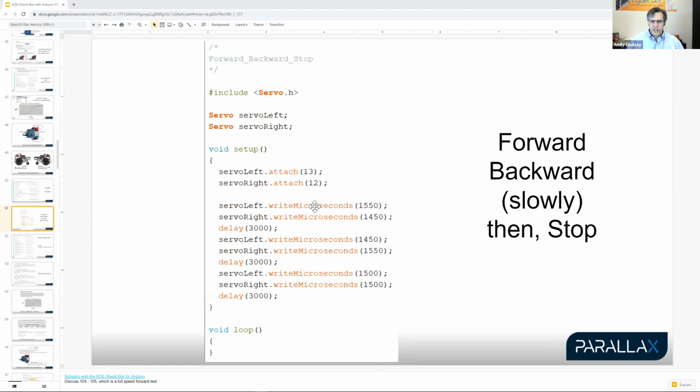So what I suggest doing first off is explaining to the students, have a delay at the beginning of your program. That's usually taken care of by the speaker, which we haven't played with yet. If you play a speaker tone at the beginning of the program for 2 seconds, then there's an ample delay during which you can move the 3-position switch from 0 to 2. So you move it from 0 to 2, it twitches, and as it's beeping, you set it down, and then off you go. That's the easiest, least classroom management intensive approach, is just to get all the students in the habit of doing that.